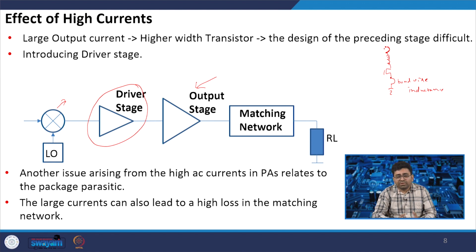So, our efficiency will reduce due to these parasitics also, and if we try to make the matching network on chip, that will also add too much loss, because we have already seen that inductors and transformers are lossy. So, in many cases all the matching network needs to be designed off chip, so that the loss will be reduced and that will give high power.